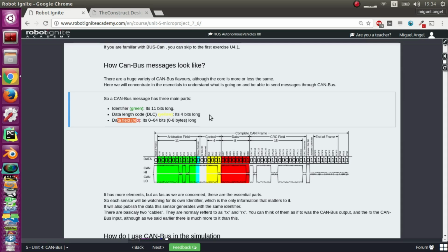So you learn that now, using the CAN bus, you will publish in some topics that are real, let's say steering, throttle pedal, brake pedal, and gear selection, and this will be transformed into CAN information and transmitted through the CAN bus to the car systems. And the car will return data in CAN protocol also, and you'll have to transform that information to information that you can understand and publish in a topic. But that's the real way of doing things. It's not through topics. The vast majority of information will be transmitted through the CAN bus.